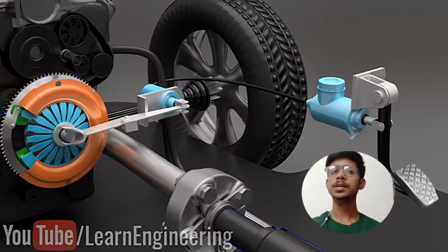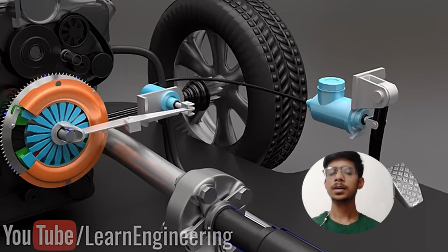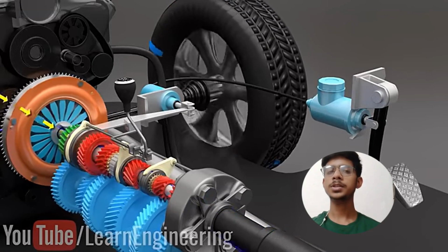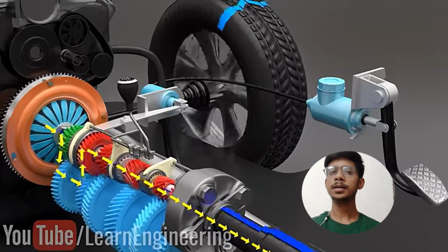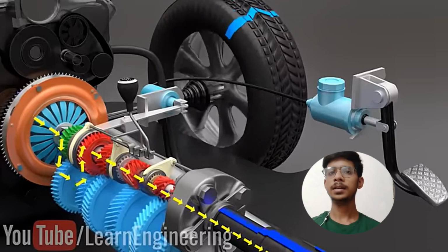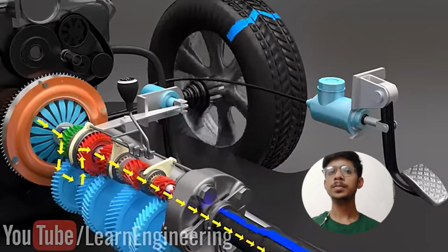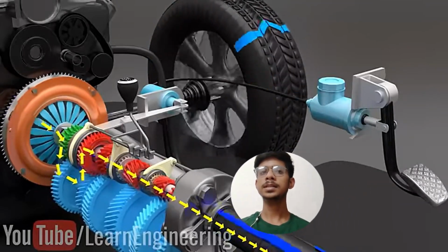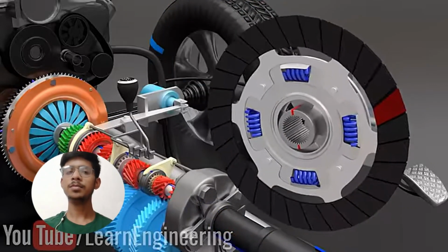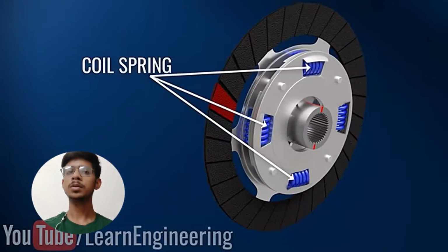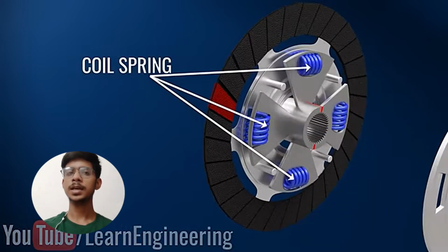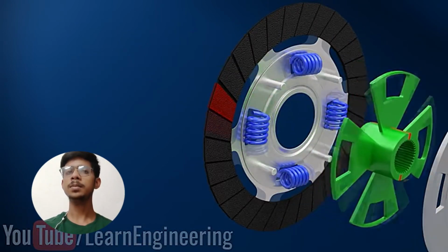In an actual clutch, you can see a few coil springs on the clutch disc. These are used to smooth out most of the fluctuation and vibration from the engine output. It is clear that the hub and disc are not directly connected. The power output from the engine first reaches the disc, then transfers to the spring and finally to the output hub. This means that the spring will dampen out most of the power flow fluctuation and the motion transfer to the vehicle will be much smoother.